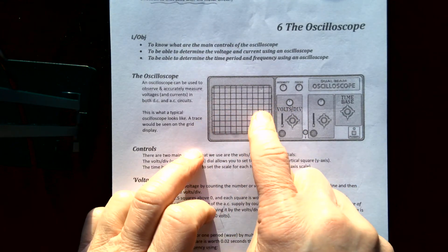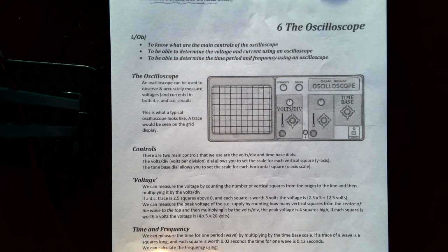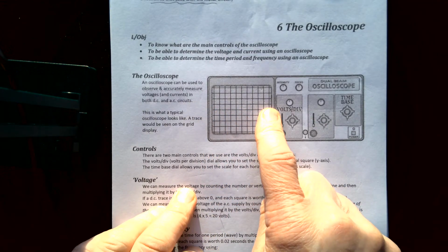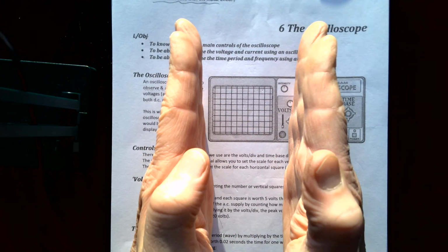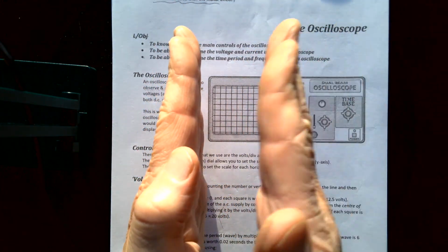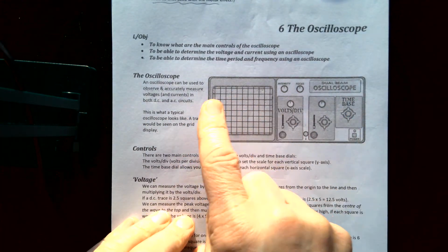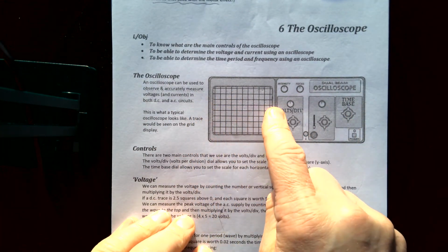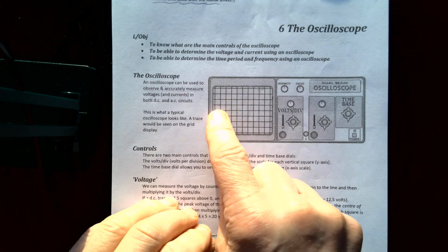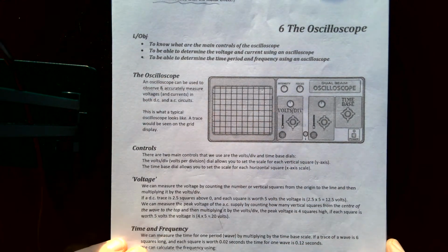We move the dot across the screen using one of the controls, and there are two sets of controls. The time base is the time it takes to go across, and that uses a pair of electric plates. Our electrons are firing towards you, and they're being pushed to the left or to the right. That's always changing, so your dot sweeps across, jumps back, sweeps across, jumps back. So you're only seeing the end of a single beam of electrons being fired at the screen. Have a look at the PowerPoint, it's quite interesting.